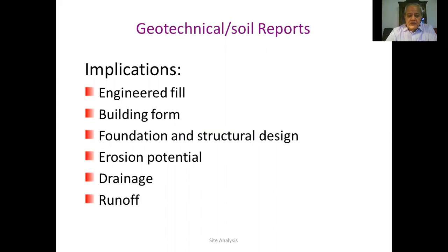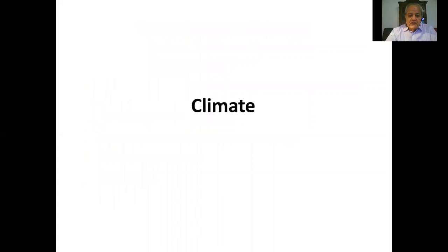All this information has impact on the design and the construction. Do we need to have engineered fill? Do we need to consider the building form with the soil types, the types of foundation and structural system, erosion potential, drainage, runoff? All these are implications that happen from the soil.